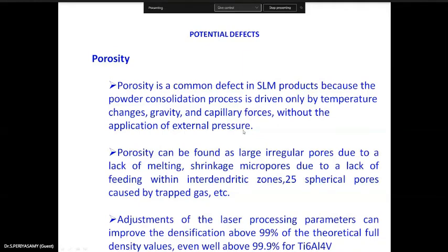So here, what happened? We are adding something additional. With the scanner, images will be taken continuously, and a camera is focused on the particular part. So what happens in selective laser melting? Here the part is manufactured, and this will be continuously monitored by an infrared camera as well as other scanning devices. It will be continuously scanned. Then you can tell whether melting has happened or not.